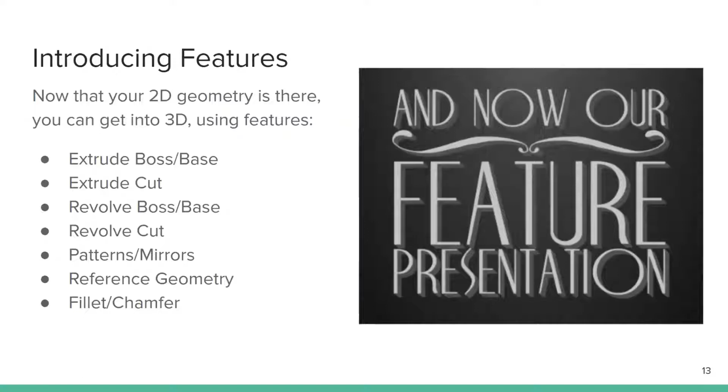And extruded cut would essentially perform the same action where it takes this two-dimensional square and projects it out into 3D space. But instead of creating matter, it would eat through anything it intersected. So if you had made other 3D stuff previously, then it would chop through all that.